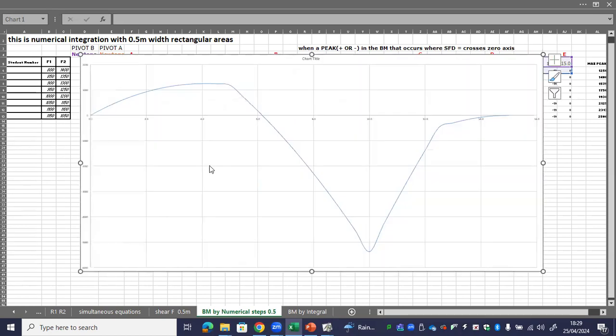Now we can see our bending moment diagram is curved. It's an x squared function. It's not straight lines, it's parabolic. So we increase the bending moment through the first 0 to 5 meters. And then the bending moment goes very negative down here, and then gradually comes back up, goes back to 0 at 15 meters as it should do. Now we've got positive and we've got negative bending moments in here. So we can have some conclusions out of that which we'll come to at the end.